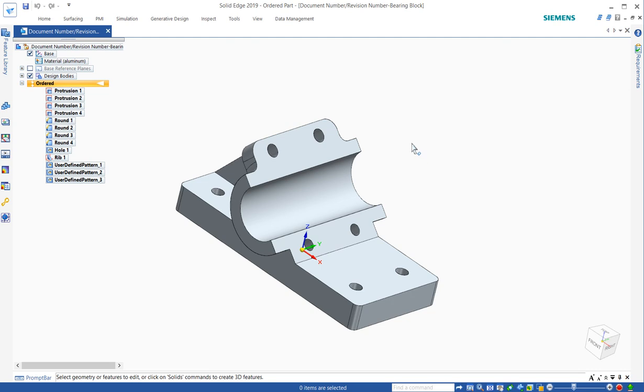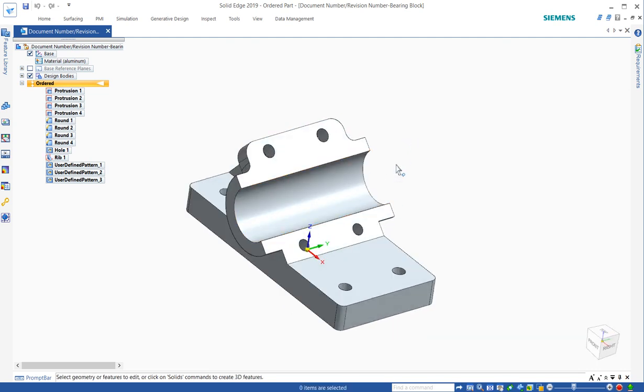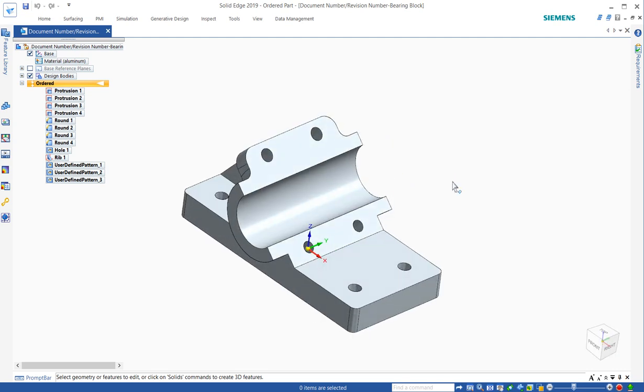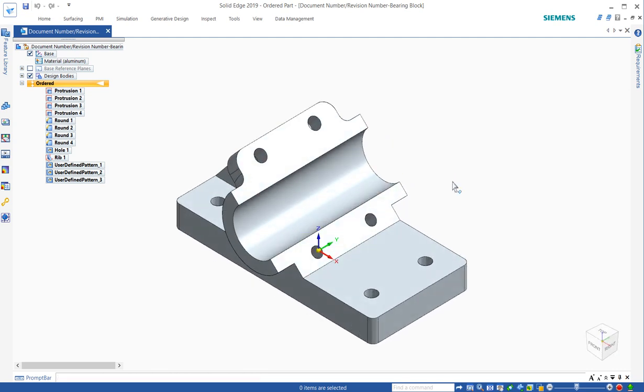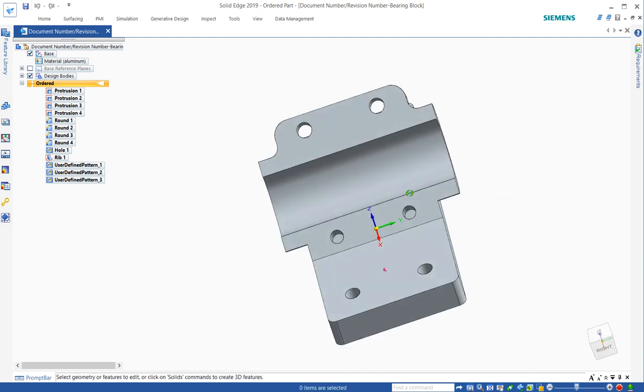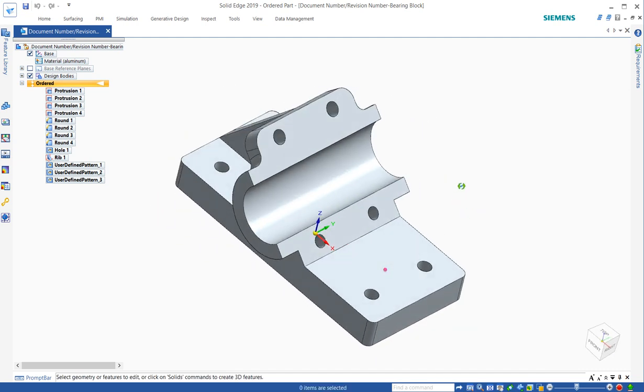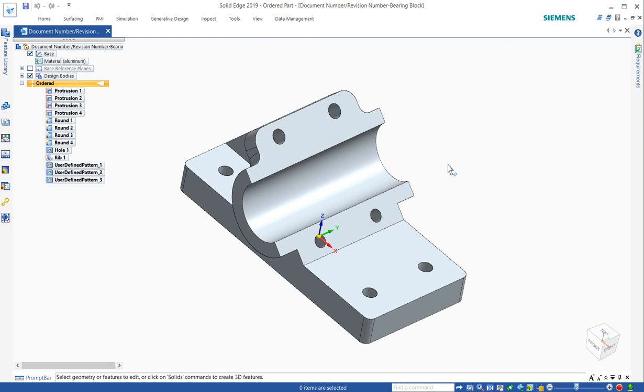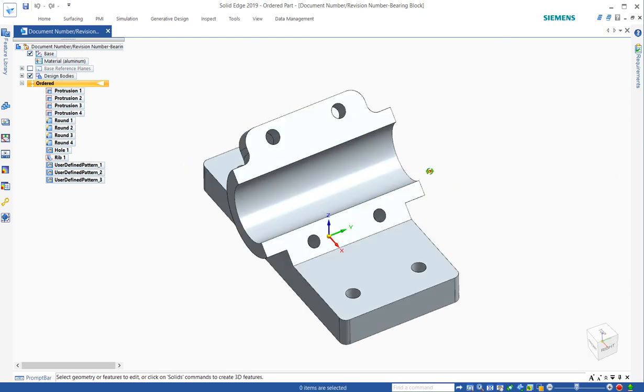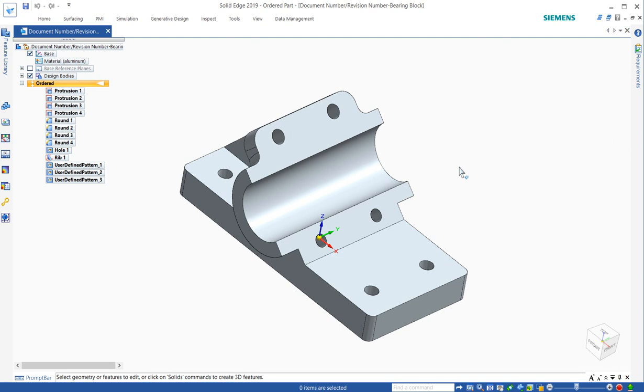If you pick a circular edge, it will become locked to that. And then people ask, how do I get out of it? How do I make it stop? If you middle click in space, because your mouse didn't land on any geometry, it resets it back to the scene center. Or when you do another command like Control-I, that will also clear it. So you do middle mouse click, and that sets the rotate point. That is extremely productive, especially in assembly. So I would get proficient at that.